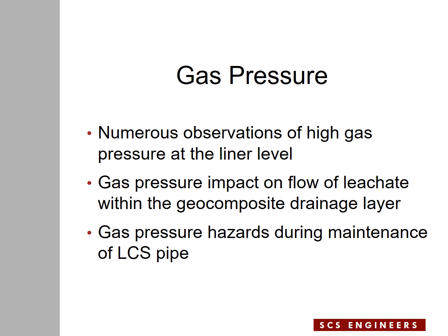Also, gas pressures could generate hazards during maintenance of the LCS pipe, which could be removal of submersible pumps from the riser pipes for maintenance purposes, or performing pipe cleaning using high pressure nozzles.